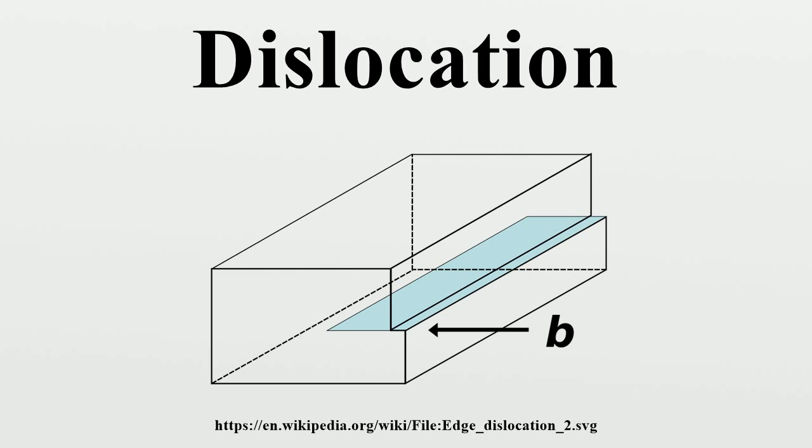Field ion microscopy and atom probe techniques offer methods of producing much higher magnifications and permit the observation of dislocations at an atomic level, where surface relief can be resolved to the level of an atomic step. Screw dislocations appear as distinctive spiral features, thus revealing an important mechanism of crystal growth. Where there is a surface step, atoms can more easily add to the crystal, and the surface step associated with a screw dislocation is never destroyed no matter how many atoms are added to it.